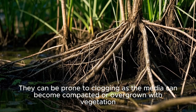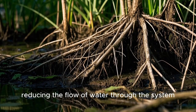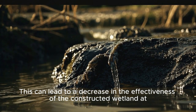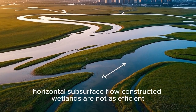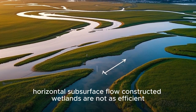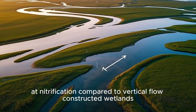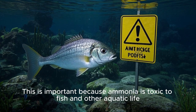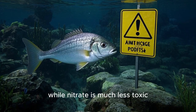They can be prone to clogging, as the media can become compacted or overgrown with vegetation, reducing the flow of water through the system. This can lead to a decrease in the effectiveness of the constructed wetland at removing pollutants from the water. Additionally, horizontal subsurface flow constructed wetlands are not as efficient at nitrification compared to vertical flow constructed wetlands. Nitrification is the process by which ammonia in the wastewater is oxidized to nitrate. This is important because ammonia is toxic to fish and other aquatic life, while nitrate is much less toxic.